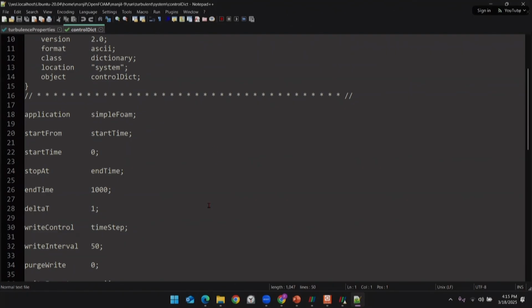Sir, in my case, ParaView is not directly getting launched. It was a problem since yesterday. What I have to do is touch result.foam and save it to some other folder, and then from there I have to open ParaView. But when I'm doing this, it is showing multiple options to open. When I'm dragging to open, it is showing a reader.